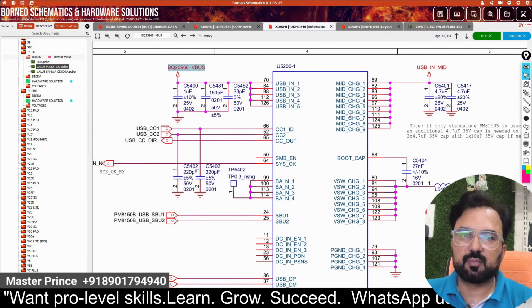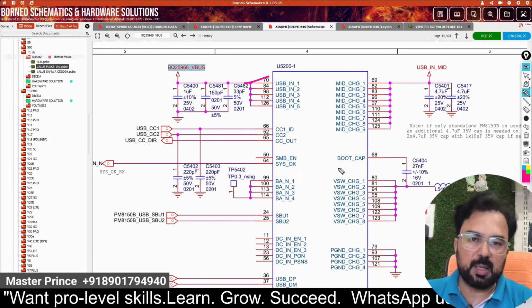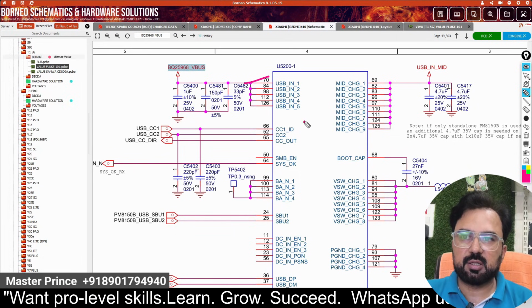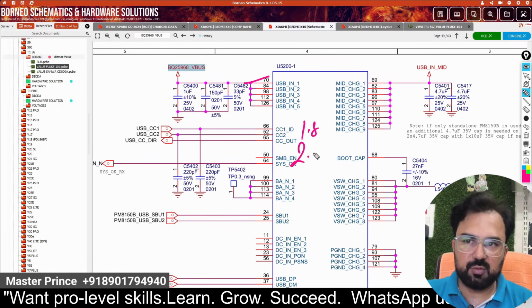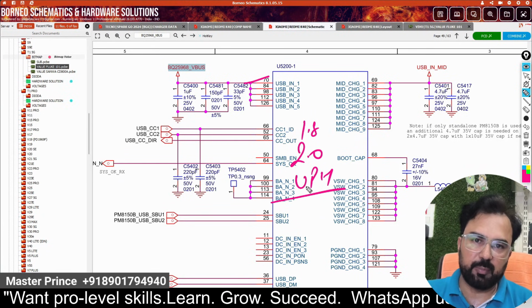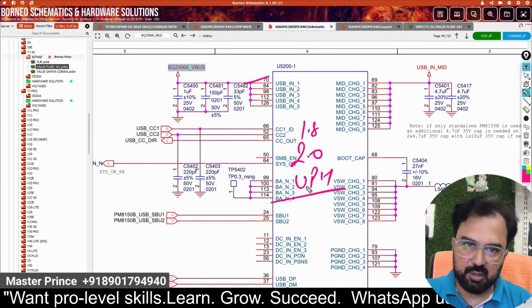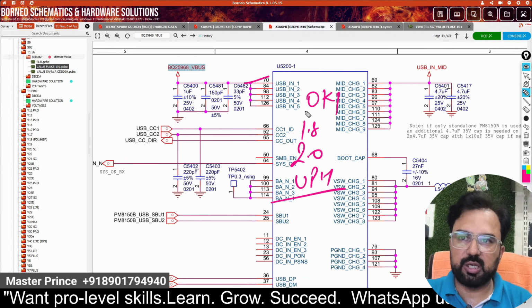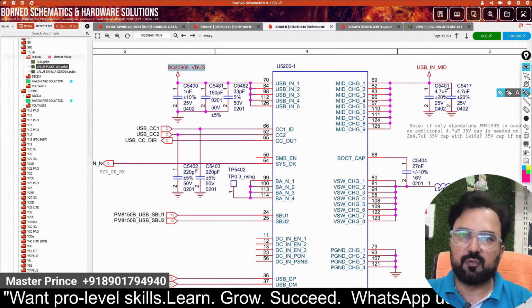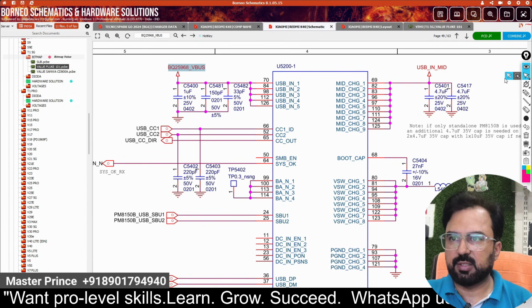Here V bus in, the boost cap is switching, that's why it's taking 1.8 ampere at 2.0, and VPH is also generated because the phone is turning on properly. It's working in charger mode and also in battery mode properly. So this IC is okay. We do not need to test, or you can say check, this IC. The fault must be in the secondary IC.